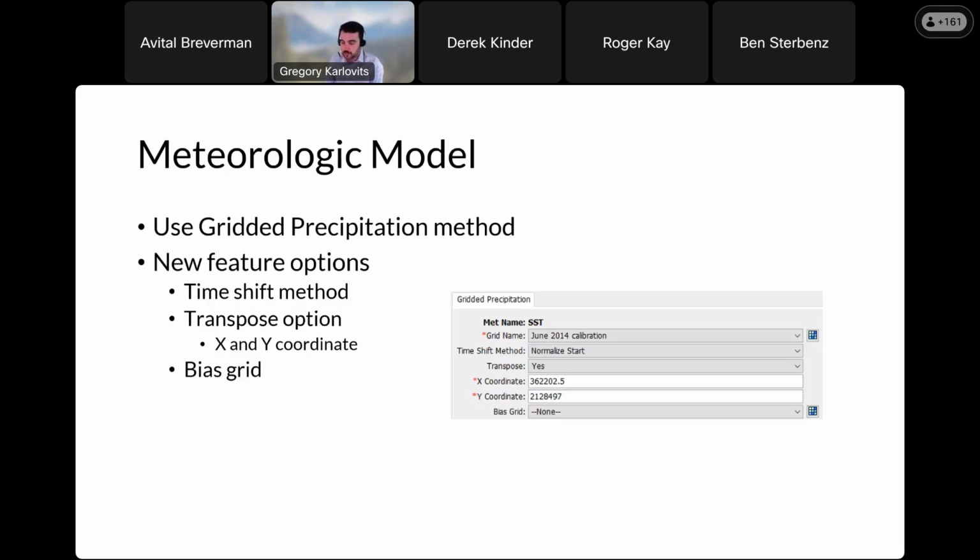A lot of times we use things like PRISM normal precipitation or the NOAA Atlas 14 100-year rainfall. But what this lets you do is account for climatic variation within a transposition region. This still makes it important for you to draw a good transposition region, but it relaxes how strict those boundaries are a little bit, because now you can deal with things like gentle gradients of rainfall,